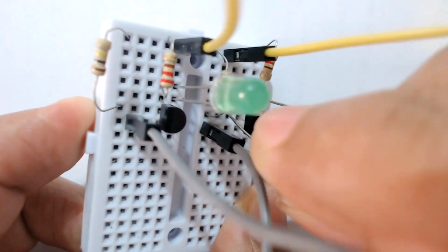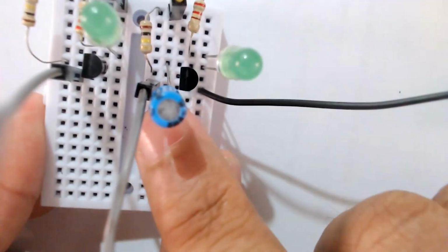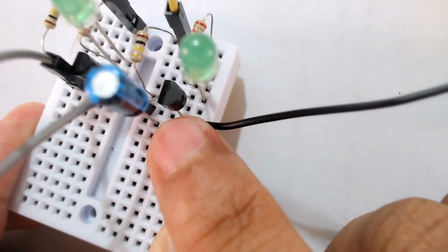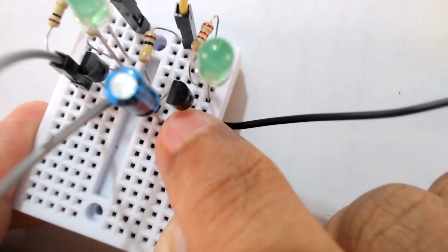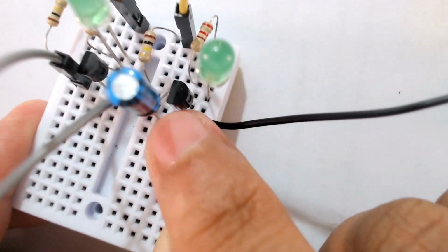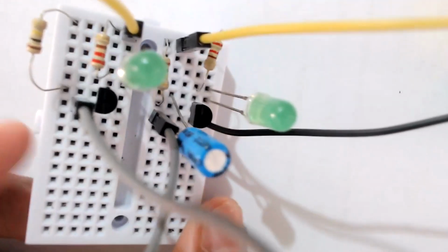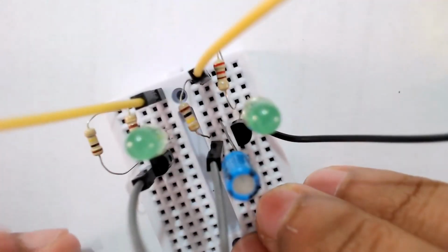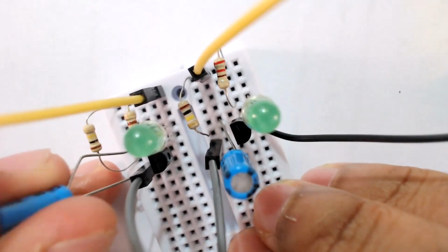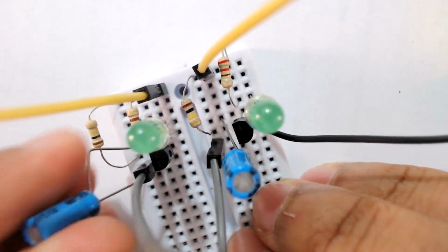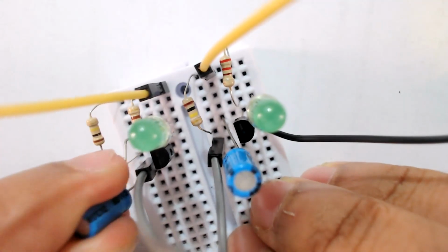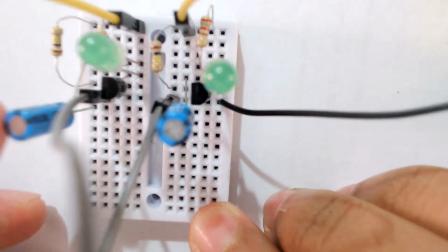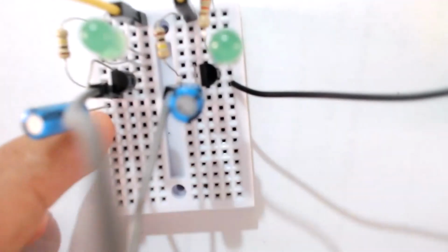Bring the other one down this way. Right? So the other side is not connected to the one connected to the emitter; it goes to the collector on the upper side. I'm going to repeat the same process for the other side. The longer terminal is connected to the collector. The other one is connected to one of the free rows available, right? Then this negative terminal must be connected to the base of the other side.